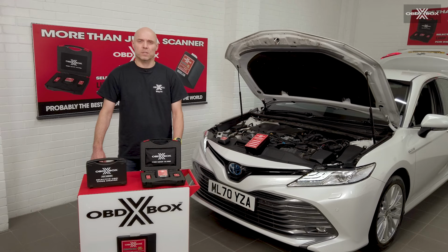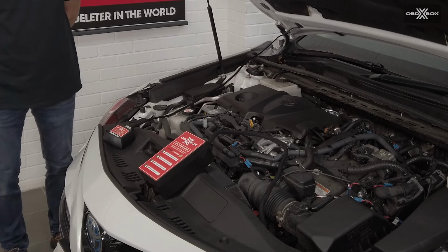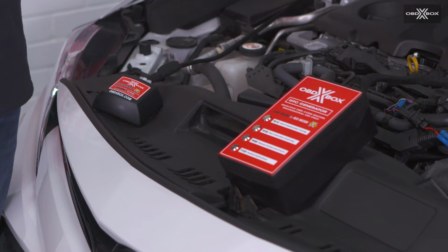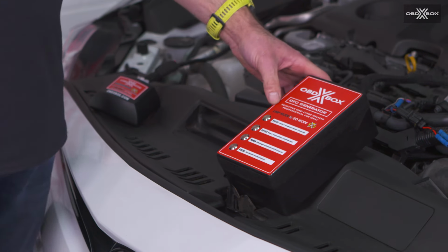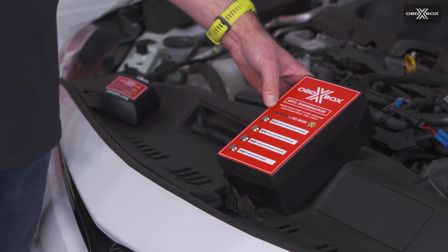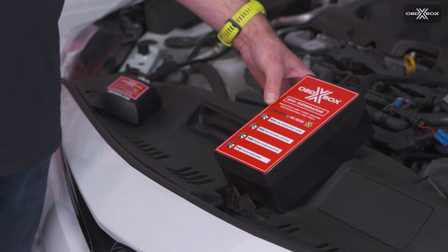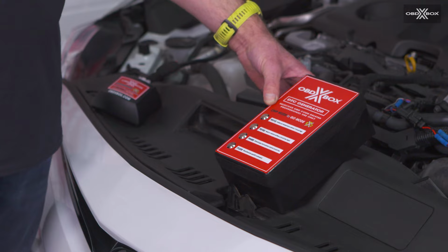It's designed to work on cars and light commercial vehicles, predominantly using the CAN bus protocol, but there are K-line options available. Normally the technician would use the OBD X BOX from sitting inside the vehicle, but for the purposes of demonstration, we've got the unit connected into the OBD port, and we've got an interface box here to introduce faults into the system for the OBD X BOX to pick up the faults that are generated by the ECU.